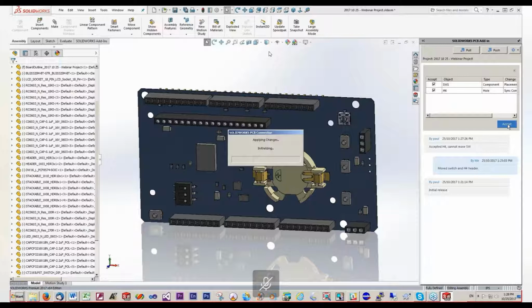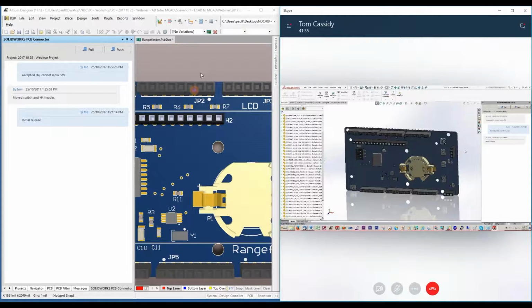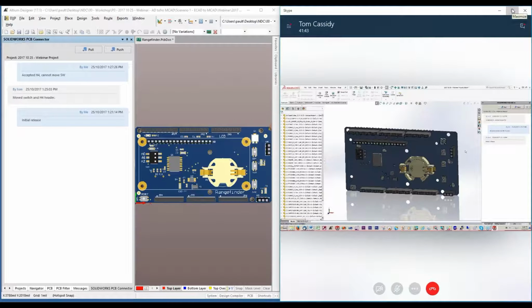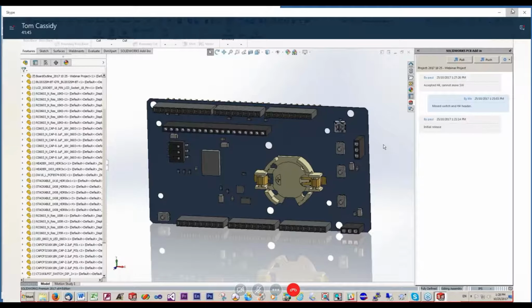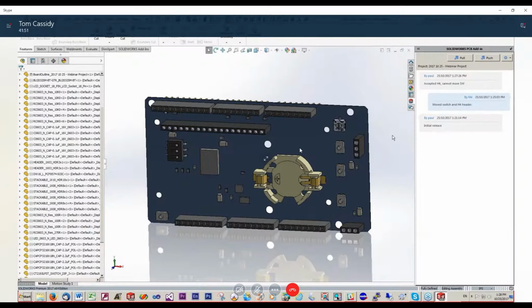Yeah, in fact, I'll split it for just a moment so we can see that. So if I go here and you view fit, then you can see that these are in the exact same place again. And again, we can do this pretty much all day long. In summary, we can push those components, we can change the board size, we can add holes to the board, we can remove the holes. And by doing this, this allows the MCAD side to basically put things together.